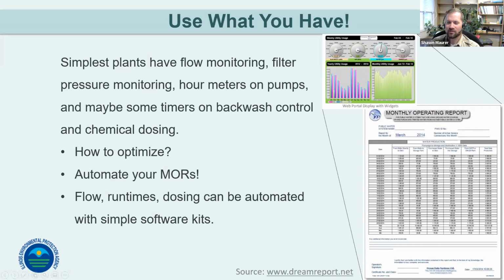Jimmy, I don't know if you've got any follow-up or additional comments on using what is already in place. Do not, other than just using the SCADA and process instruments to monitor. I'm such a fan of having process instruments. That way you can see what the demand may be on your SCADA screen and be able to adjust for that. I'm a huge fan of having process instruments. That goes for flow and anything you're monitoring. Most of the time I'm monitoring things in wastewater plants, but when you're looking for DO and ORP and pH and things like that, it's always nice to be able to see that on the SCADA screen.